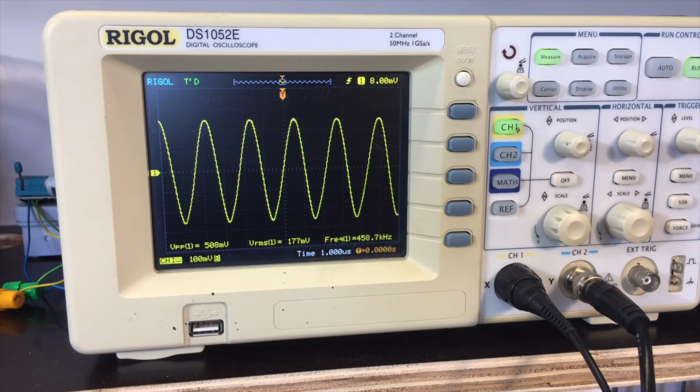Got a little bit out of that one, I think. And finally, maybe just a little bit out of that one. So our signal has peaked. We are there. We've done the full IF alignment for the AM. And that means we've done the 460 and the 2 megahertz alignment. And that means that this thing should be as optimum as can be.